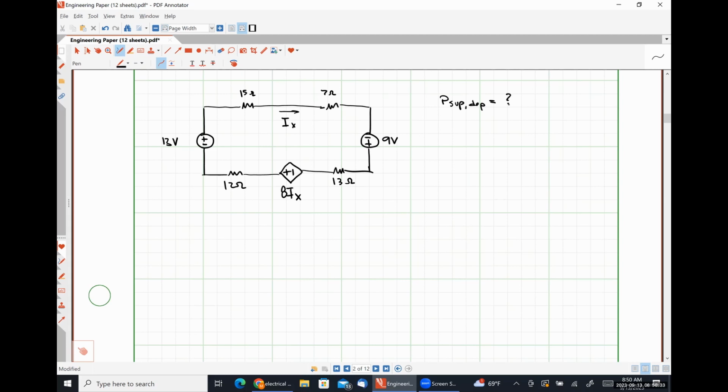So what we are going to do is apply Kirchhoff's voltage law around this circuit. This is an example of what's called a single loop circuit, where all of the different elements are connected to each other in series, so that it forms just one single loop around the circuit. Any time you see a single loop circuit, your default analysis technique should be Kirchhoff's voltage law, probably in combination with Ohm's law. Anytime it's just a single loop, KVL is going to get you practically all of the information that you want about the circuit in a step or two.